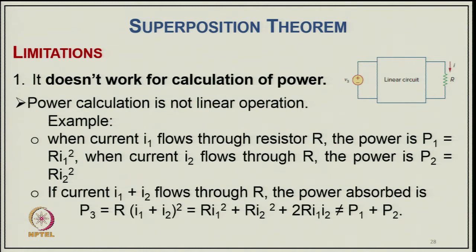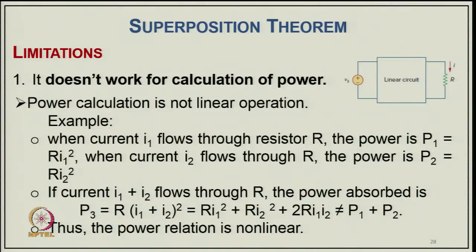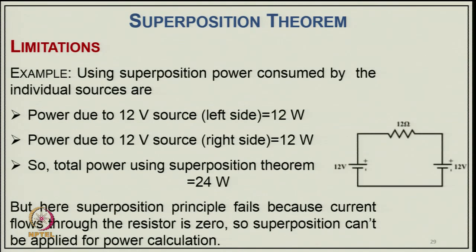So, that is the reason the superposition theorem cannot be applied for power. It is only applicable for the voltage and current relation in a linear circuit. The power relation is non-linear, so it cannot be applied for that.